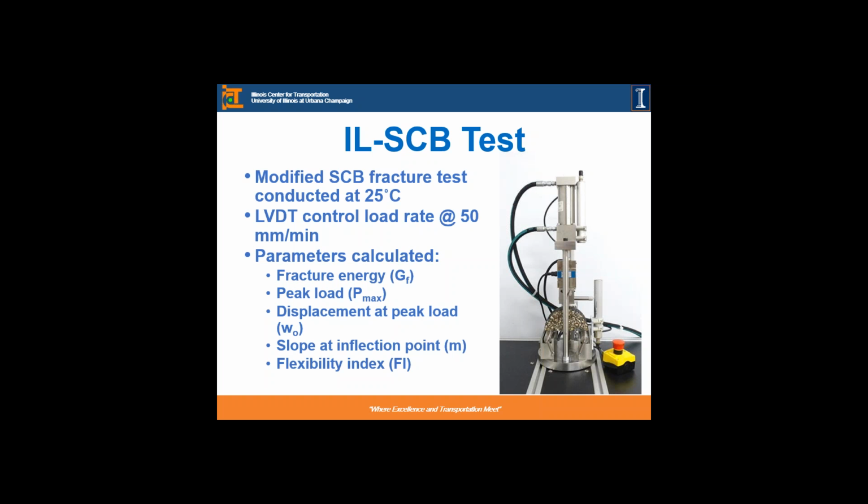The parameters that we calculate are fracture energy, peak load, displacement at peak load, slope and inflection point, and a parameter that we developed in the study, which we called flexibility index, which we use to discriminate the mix's brittleness or flexibility using this test setup. And this is one of the prototypes developed by a manufacturer before the end of the project.